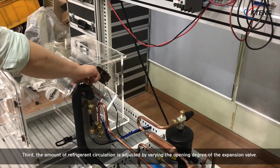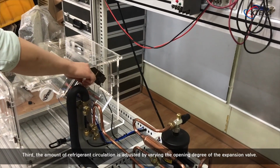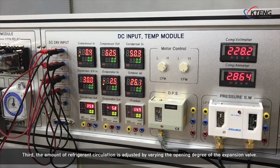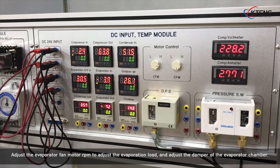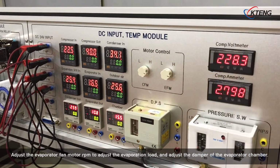Third, the amount of refrigerant circulation is adjusted by varying the opening degree of the expansion valve. Adjust the evaporator fan motor RPM to adjust the evaporation load, and adjust the damper of the evaporator chamber.